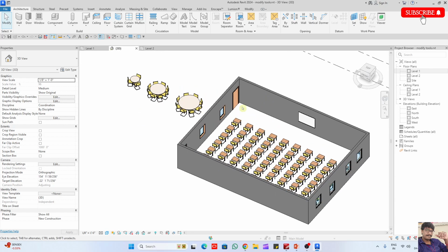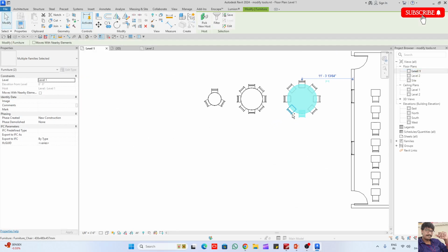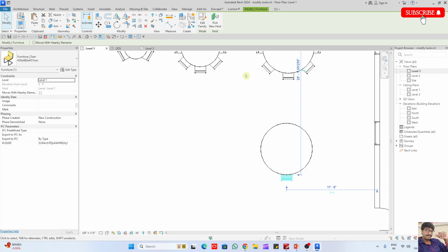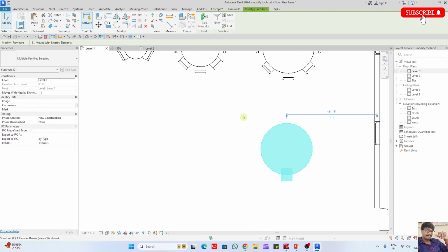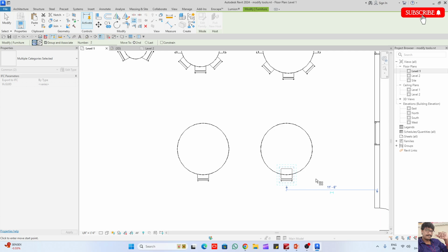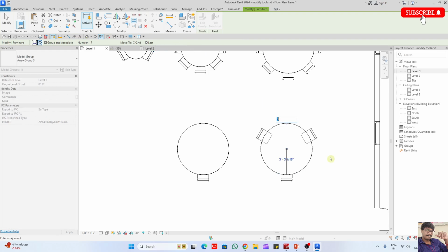Now next one, radial array. Same as what I did, select this one, copy, paste. Select the object, tell me. I'll explain both again. Select the object, AR, second array, last array. Okay, AR. Now take the radial option. Group and associative is on. Now take a center point, place. Just like the rotate command. Now second specify angle, last specify angle. So just forget it, specify last 360, enter.